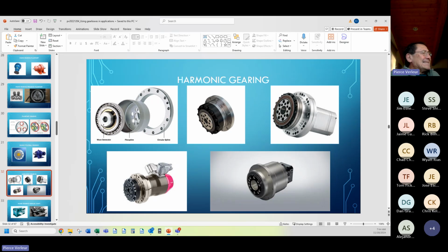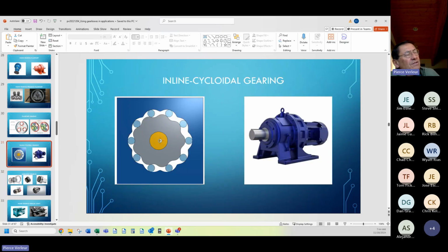Let's talk about stiffness. The stiffest gearbox is this gearbox here. Stiffness is if I put a force on this output shaft. Let's say I put a big lever arm here and I crank on it in one direction. Let me back up. I'm going to put a brake on here to hold motion, to have zero motion in the system. I needed to say that first. Then I'm going to put a huge lever arm on this output shaft, and I'm going to crank on it and put torque on this output shaft.